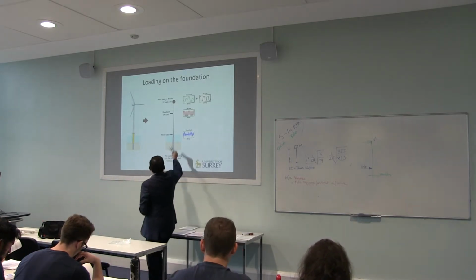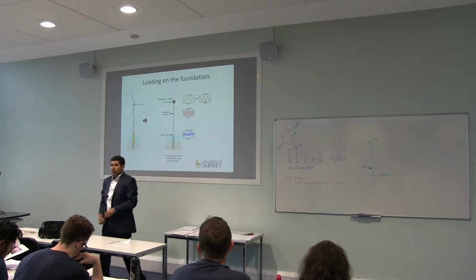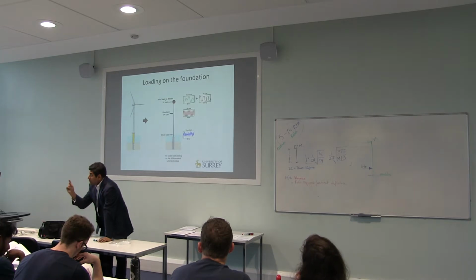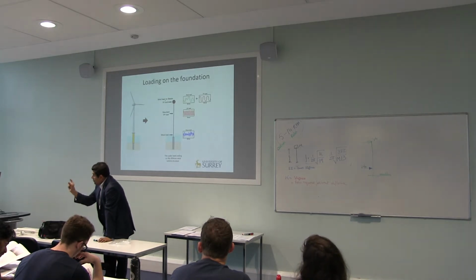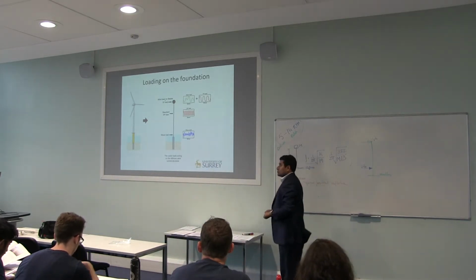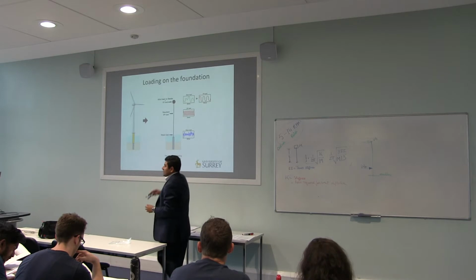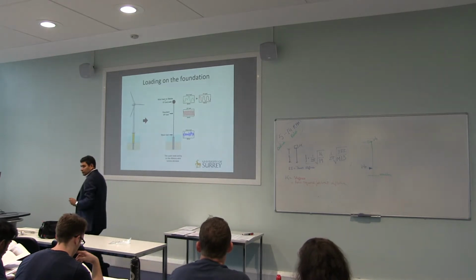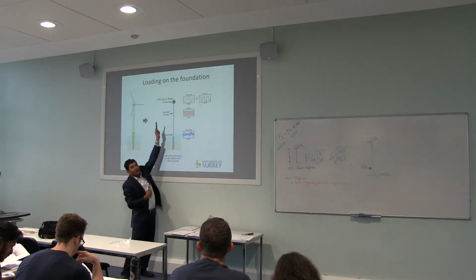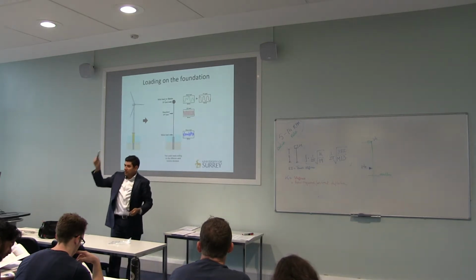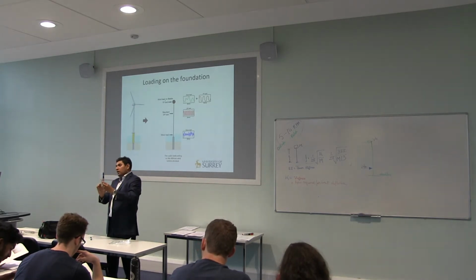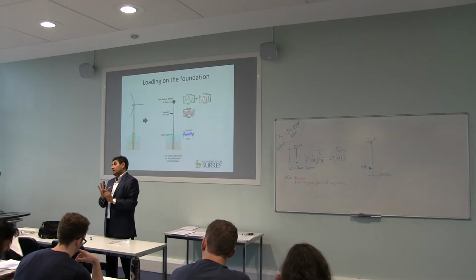Now, what is the 3P frequency? Any idea what 3P stands for? 1P means the range at which it can produce power, so 5 to 14 RPM. And what does 3P stand for? Now, this is a tall tower, a 110-meter tall tower, so the wind will blow as well. Now think of the load on the tower.